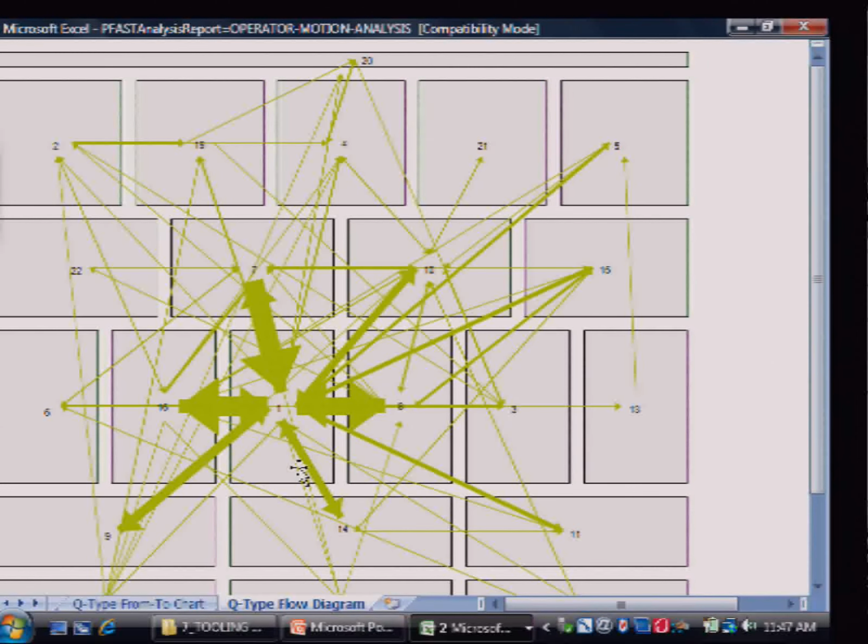So naturally, from an ergonomics point of view, you would, one, want to put those locations next to each other, and two, you would like to put them in the favored comfort zone of the operator. That is, if they are right-handed, you would like those zones to be on the right side of their body. If they're left-handed, you would like those zones to be on the left. What you don't want is that the heavily utilized locations where the person stands and the other locations to be behind, because then the torso will experience a lot of wrenching. So this is basically what FAST spits out.